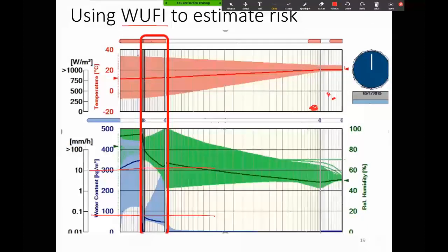I'm going to have a line here. If you can see that, for my drywall, I'm going to have a line that starts here, and then for my cavity insulation, I'm going to have a thickness associated with that. And so that line is going to stop over here. That's going to represent my cavity insulation. And then I'm going to have a line for my vapor control layer, and then for my exterior insulation, and then for my siding, and so on.